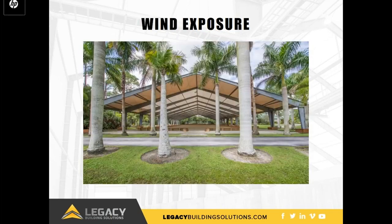Wind exposure is dictated by the surface obstructions around the building. For example, buildings in densely built or wooded areas will have a different wind exposure factor than buildings not protected by other buildings or trees. Ensuring that the proper wind exposure category is used for the site location of the building is an important part of the design engineering for a building.